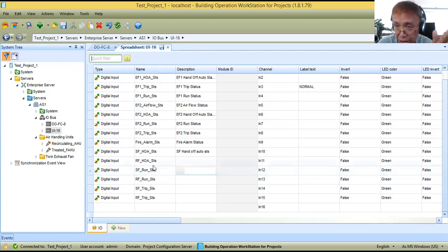I guess it's already clear for you. Once you specified it in your DDC IO modules, then the next part is you will ask your technician to pull cable from these IO modules going to the motor control.